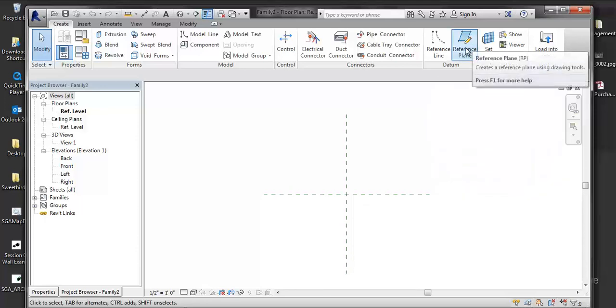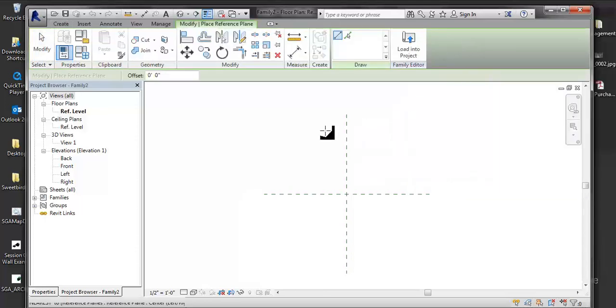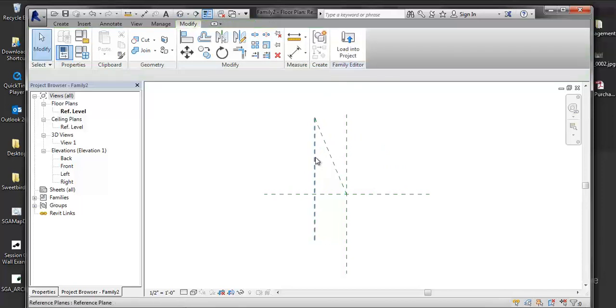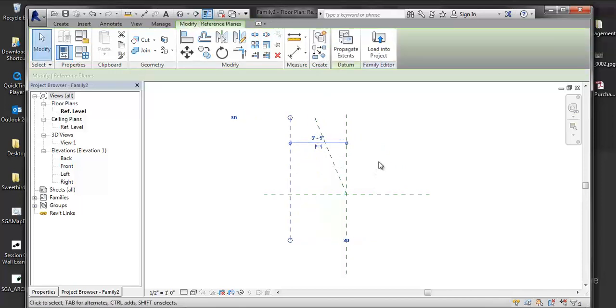And the reason for that is, again, if I do RP on the reference plane and try to snap to the end, I can obviously snap there. But the minute I move that reference line, it's not snapping that plane to the end of that line. And that's because even though you see it graphically as a start and end condition, it's more like a ray, not A-R-R-A-Y, but A space R-A-Y in CAD, where it goes into infinite space. It's like a construction line. And that's why the angle doesn't start.